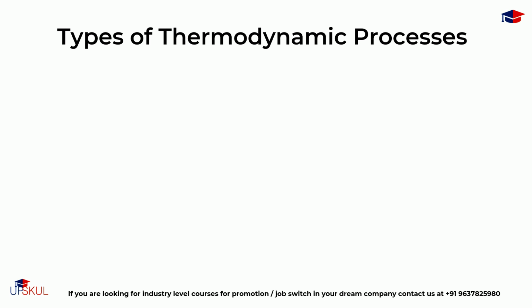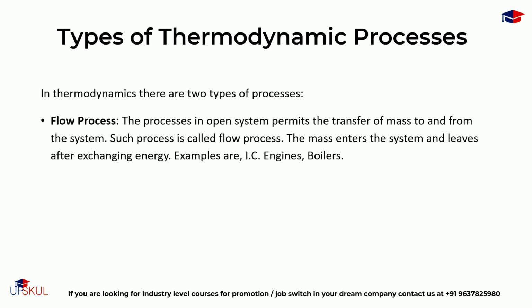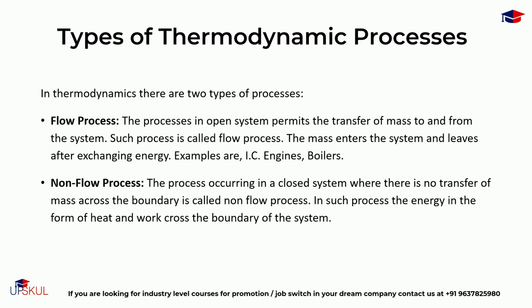Now, coming back to the thermodynamic processes that we discussed in the last video, in thermodynamics there are two types of processes: flow processes and non-flow processes. The flow process in an open system permits the transfer of mass to and from the system. Such a process is called a flow process, and the mass enters the system and leaves after exchanging energy. For example, IC engines and boilers.